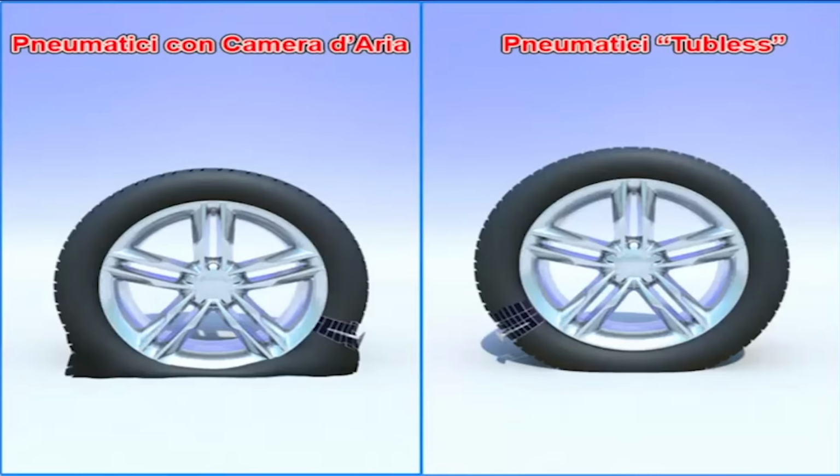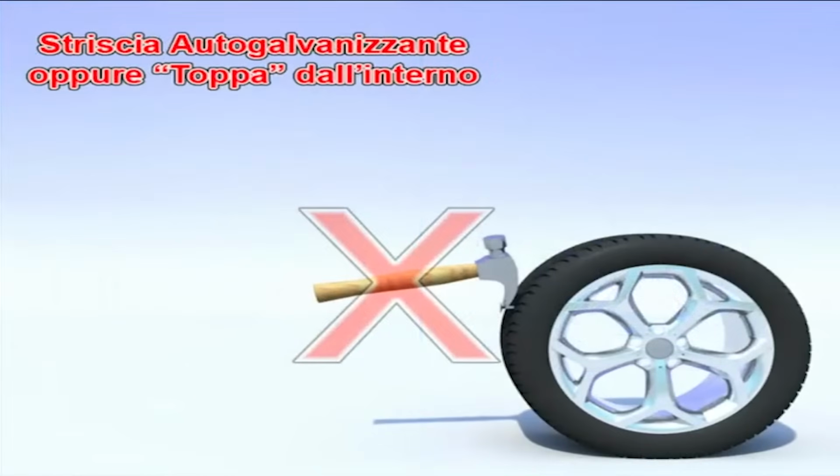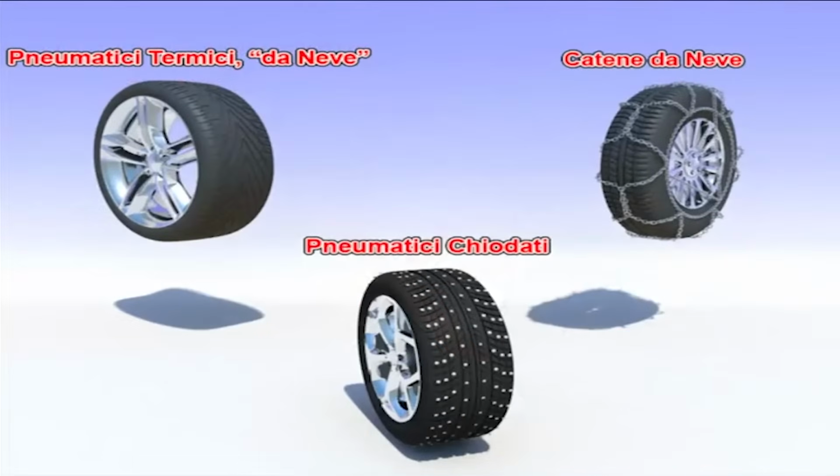In the event of a puncture of tubeless tires, deflation is slower than those with an inner tube, thus giving the possibility to continue driving, stopping as soon as possible to repair the damage. So be careful in the quizzes. In tubeless tires, you do not need to remove a stuck nail right away. Once we have safely stopped, we can repair the damage with a self-vulcanizing strip or patch from the inside.